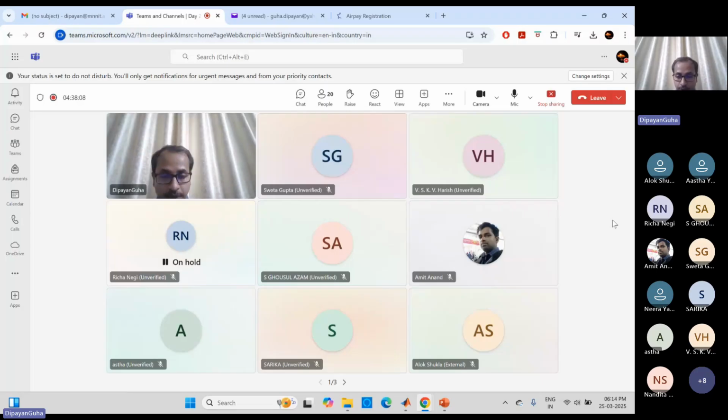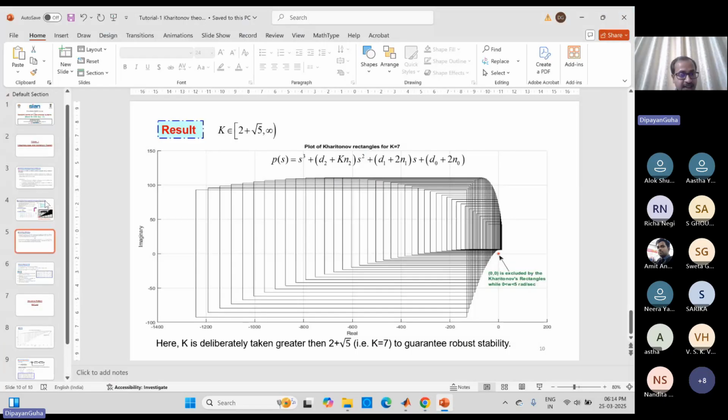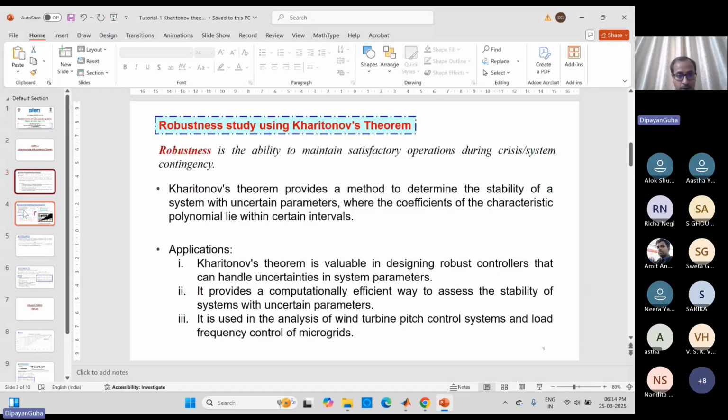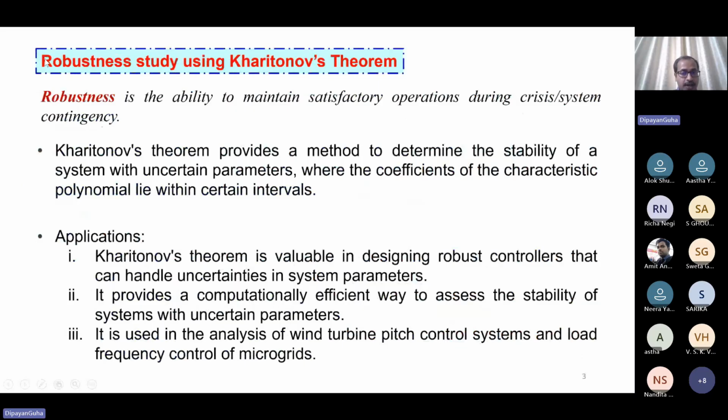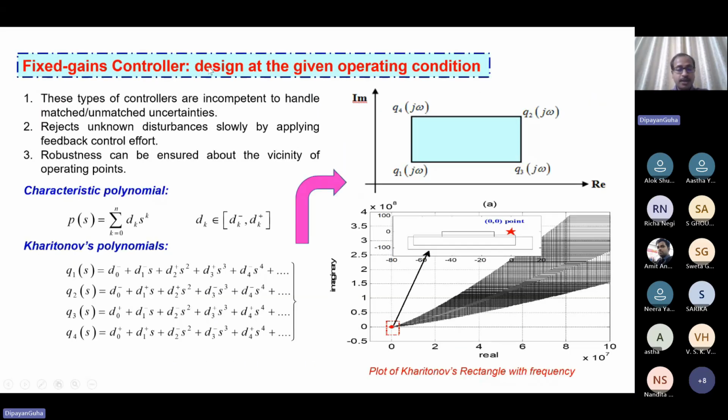So far, I don't know whether you followed the slide or not. I clearly mentioned that we are talking about the fixed gain controller. It is a fixed gain controller that I have taken into account. There are two ways of defining tuning. The number one is that beforehand you have computed the optimized value of your controller parameters by conventional or classical approaches like Ziegler-Nichols and all. Whichever method you apply for finding the controller settings, those settings are fixed only. They are not a function of time.